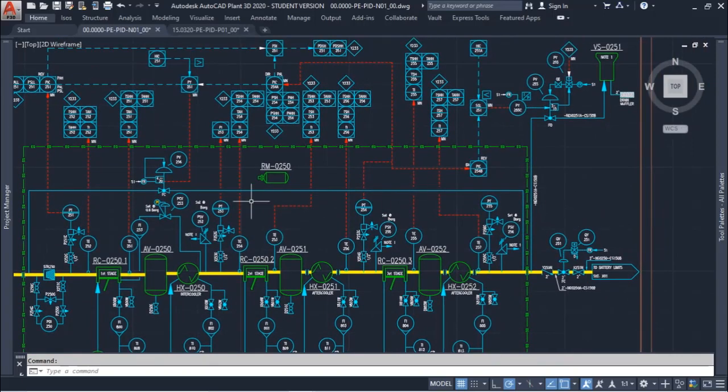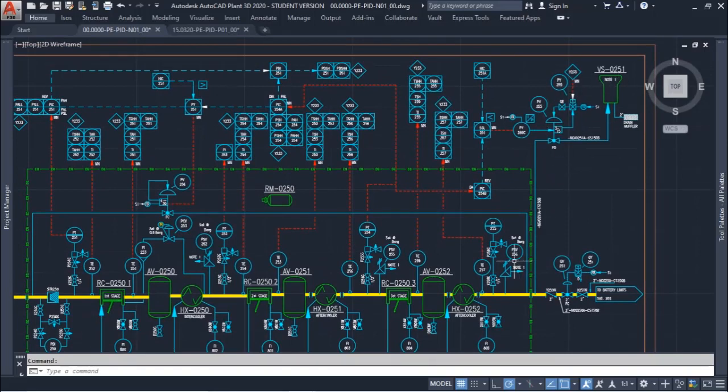And once we are closing the recirculation, the vent valve is opened to regulate the desired pressure. And in this case we could also have a sample tap for an analyzer here to guarantee that the isolation valve would open only if the gas stream is at the right requirement for the customer.